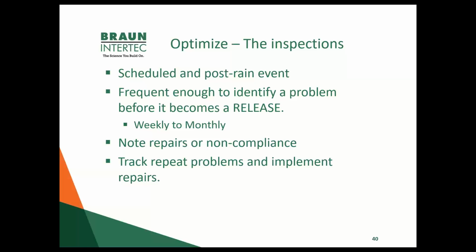Schedule your inspections when you're already doing a walk around on site. You don't have to set aside a unique time for doing your SPCC inspections. Include them with your regular maintenance or walkthroughs of the day or the month or the year. You want to do one post-rain event, so you can see how stuff flows on your site and make sure that things are flowing where they're supposed to be and not flowing where they're not supposed to be.